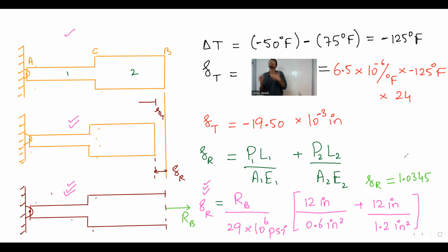If you have to find how much stresses are induced, it is complicated, because in your statics, usually there used to be a force that was applied and you used to find stresses in this class. The problem is there is no actual real force that you are seeing, but definitely when the temperature has dropped, this thing has shrunk. Hypothetically, if I remove the right support, it will shrink this much. I will pull it back and take it back to its original form. How much load I will apply in pulling it back, that will be my unknown RB.